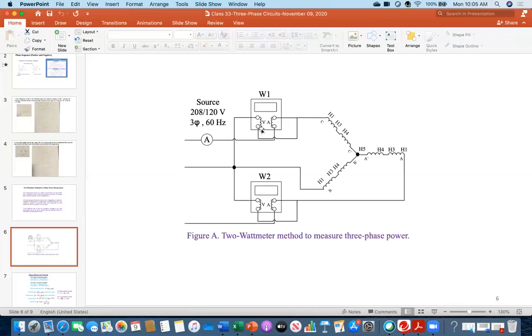But then look, for the voltmeter, one side, one port is connected with this one here, but then the other one is connected elsewhere. To measure the voltage, you need 2 points. So one point is here, this one, for this coil. You see the connection. But then the other point where you will connect it, you see here, the B phase at this point. See the bold point, dotted point.